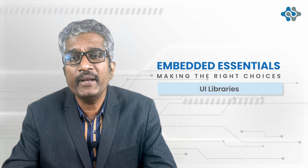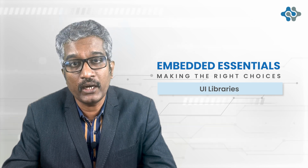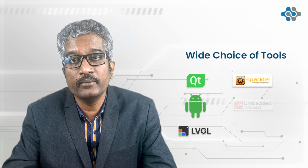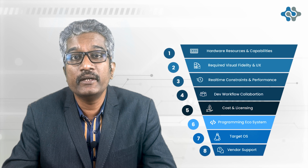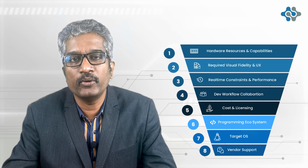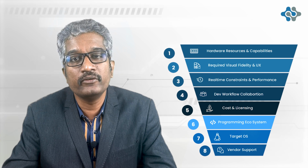Conclusion. Creating compelling user interfaces is now essential in embedded systems, but it requires navigating the constraints of your hardware. The wide choice of tools, from powerful frameworks like Qt, Android, efficient libraries like LVGL, Sparklet, to visual suites like Embedded Wizard and Flint, means there is likely a solution for your needs. By systematically evaluating based on your hardware resources, visual requirements, performance needs, development workflow, cost, language, OS, and support, you can choose the embedded UI tool that lets you build beautiful interfaces successfully within your product's limitations. I hope this framework helps you select the right graphics tool for your next embedded product.